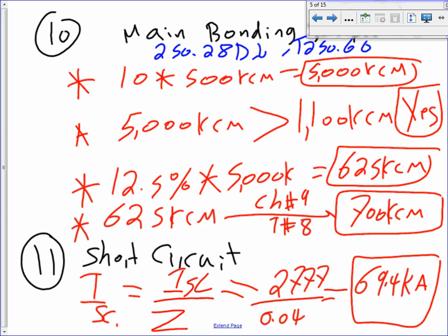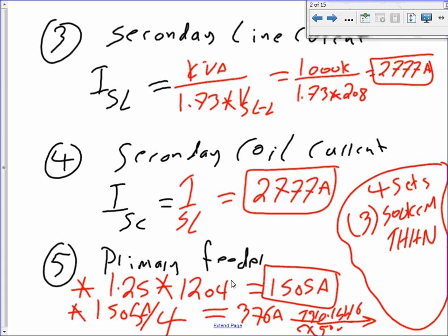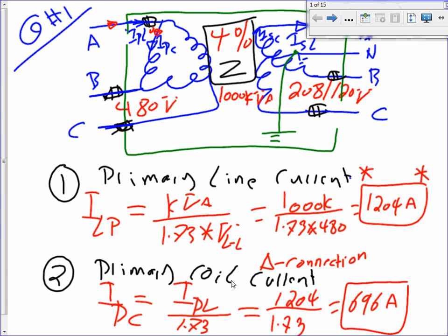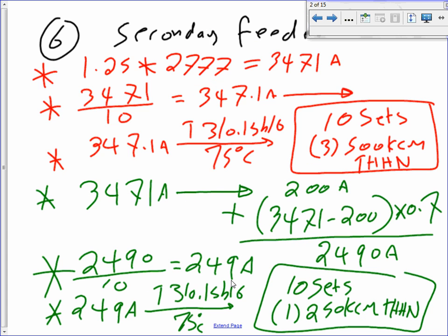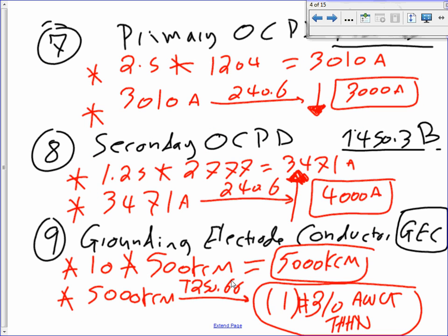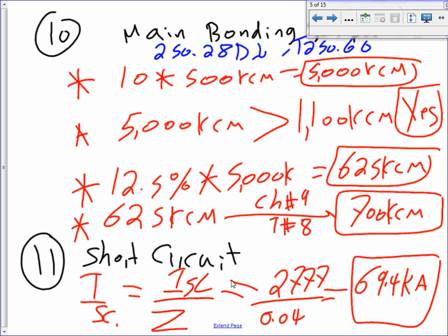The 0.04 is given to you by your friend Chad. It's that 4% impedance. Z is the impedance of a transformer. What does it mean? Like Adam said, Chad, you didn't do it before because it's coming next project. Z, guys, will decide how much short circuit the impedance will allow to go through your building. Major thing. This is the available short circuit.